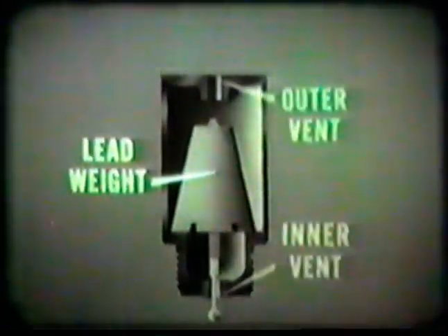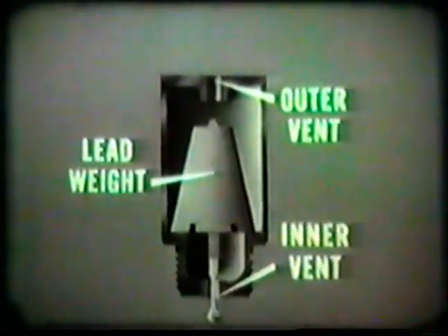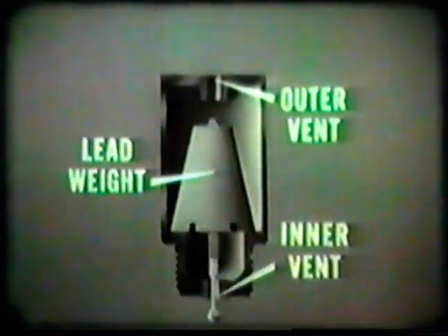This cap is different from the caps found on an automobile battery. On the outside, the cap seems quite similar. However, when it is cut in two, we find that it is hollow and contains a lead weight. At each end of the cap, there is a vent hole. When the battery is in normal position, the vent holes are open, permitting gas formed in the battery to escape.